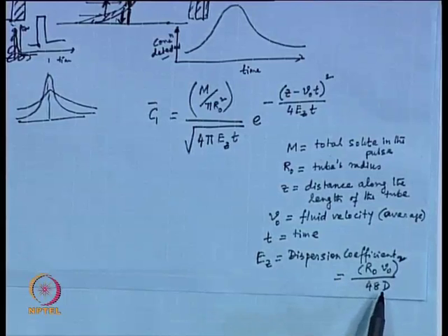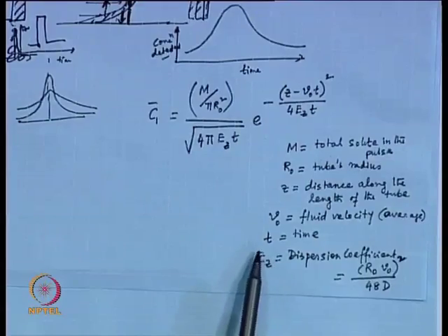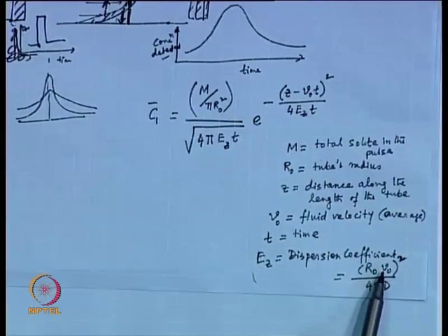Okay. So, d is in the denominator, and earlier E z was equivalent to d. So, that time d was in the numerator. That means d has an inverse effect. Whatever effect d had on the diffusion of a spot of tracer in infinite medium, here the diffusion coefficient is doing just the opposite. Do you appreciate? Because d is in the denominator, if d increases, the process goes the other way, and there if d increases, the process goes in some other way. So, this effect of d is completely different, and another factor is that this E z, which is equivalent to d, is dependent on V0 square.